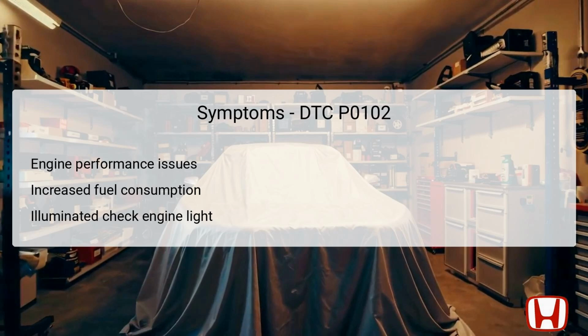Increased fuel consumption is another common issue, as the engine may compensate for perceived low air intake by injecting more fuel than necessary. Furthermore, the illuminated check engine light on the dashboard acts as a warning indicator, alerting the driver to the current issue. Each of these symptoms not only affects driving comfort, but could also contribute to long-term engine wear if left unresolved.